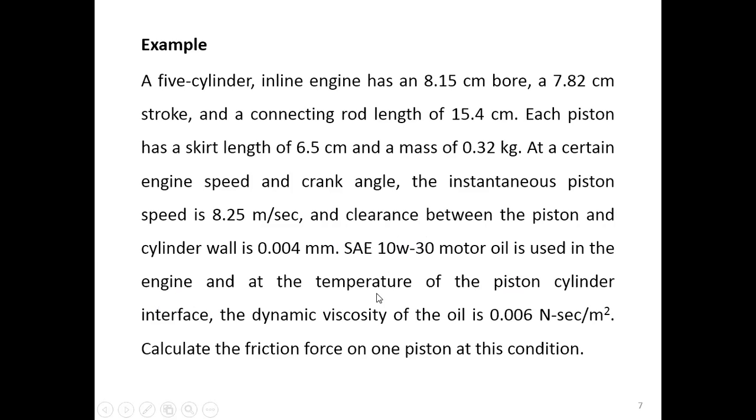And the temperature of the piston cylinder interface, that means at the temperature of the clearance area here, the dynamic viscosity of the oil is 0.006 Newton second per square meter, because the dynamic viscosity changes with the temperature. That's why they mentioned that at this temperature, the dynamic viscosity of the oil is 0.006 Newton second per square meter.